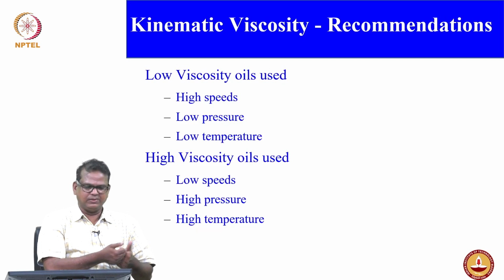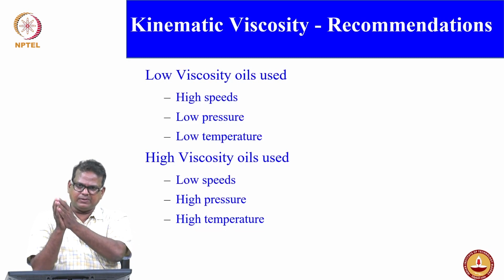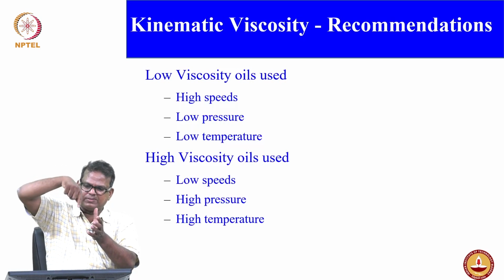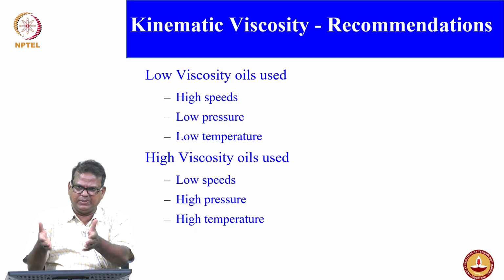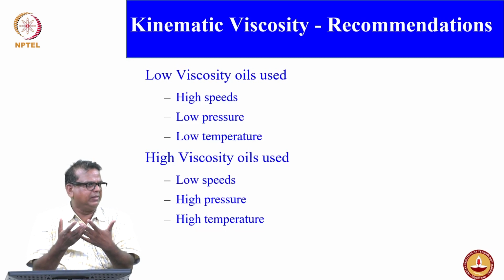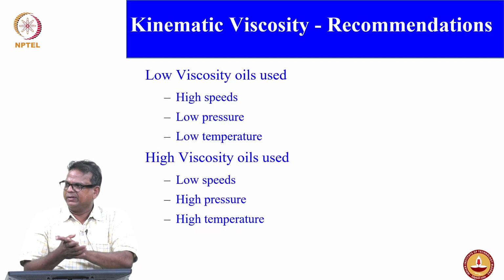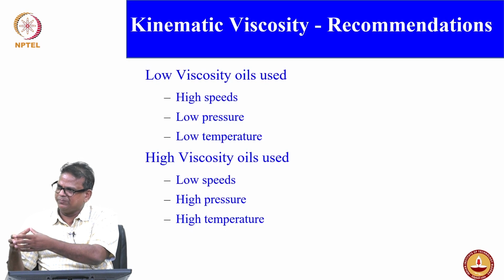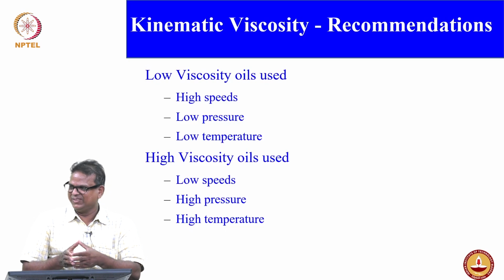The reason is, if you choose a higher viscous lubricant for a higher speed application, assuming gear is there and you have taken very thick oil, if the gear is rotating in the thick oil for a few minutes, what happens? The shearing within the lubricant will give internal heating. Internal heating will in turn increase the heat. The moment heat increases, what happens to your viscosity? It reduces.